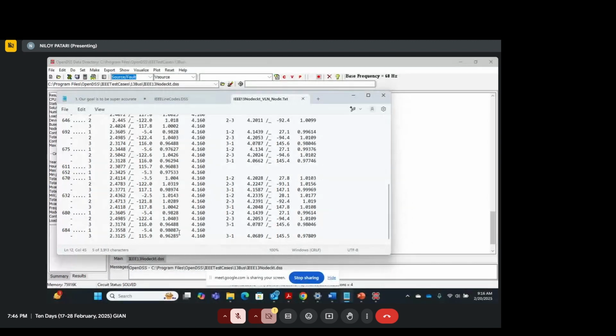Obviously, if you go into a bit more detail, you can find standards where, under emergency conditions or under different conditions, it says how much voltage dip or voltage boost you can allow. You can find that online, but it will be definitely below 0.95. It will say that you can go below 0.92 or just stay above 0.9 per unit for this amount of time and all of that. Those are standards for power engineers, but just for your knowledge, for steady state, we try to keep bus voltages within that plus minus 5%.